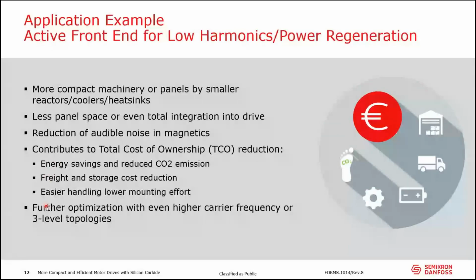And this example was just adjusted to 20 kilohertz, selected to meet the thermal conditions of the IGBT. It's not optimized. You can even optimize the carrier frequency and find the sweet spot between size of the choke and everything that is in that system here.